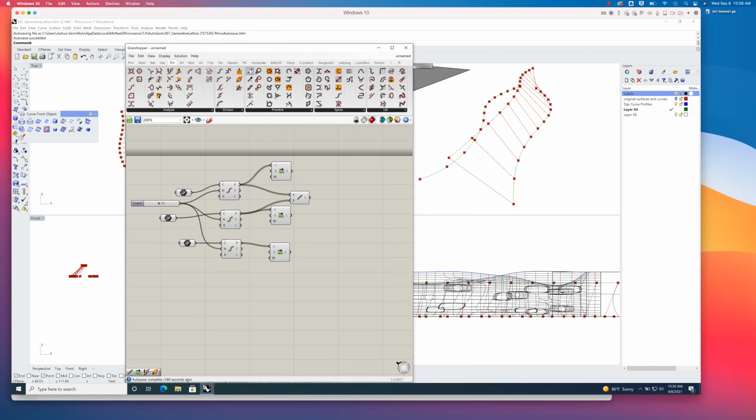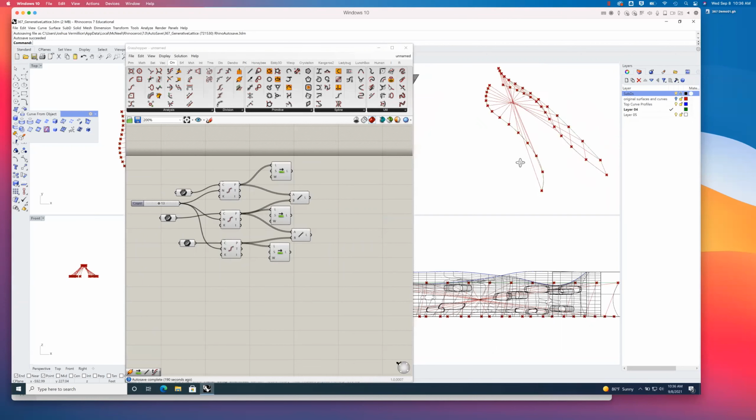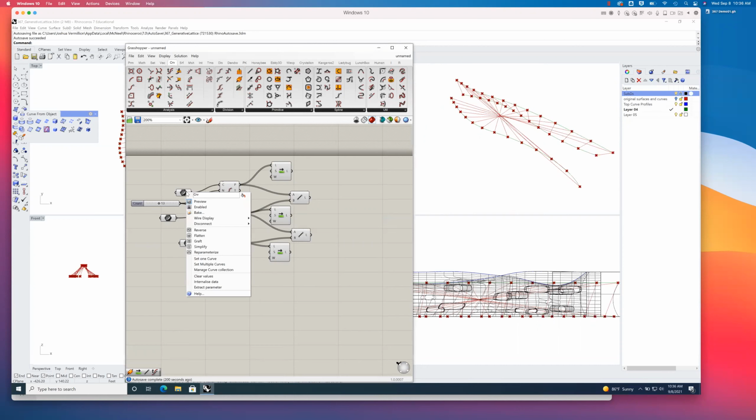All right. I'll do the same thing between these and these. And then last, now look at this. What happened here? Anybody, did this happen to anybody? So what's interesting is, first of all, when you make a curve or a line, Rhino remembers what the start point and end points were, in the order that you clicked. And also when you set these, it remembers the side that you clicked on.